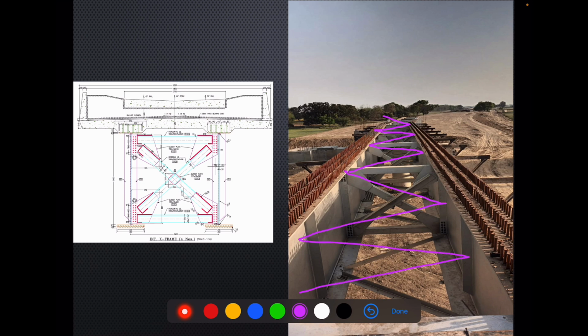Here they are not required because this stiffness is achieved with the help of this deck slab, right? They are permanently cast into my deck slab. They are quite integrated with the help of these shear studs. These are called shear studs. So this is how the arrangement of a composite steel plate girder looks like when we see the intermediate portion of the girders.